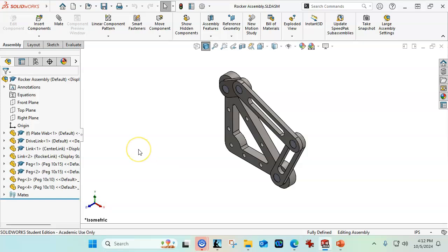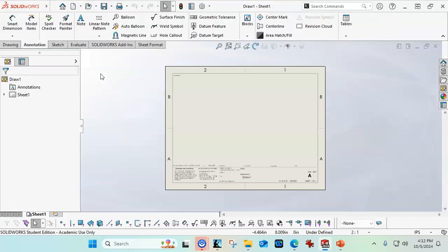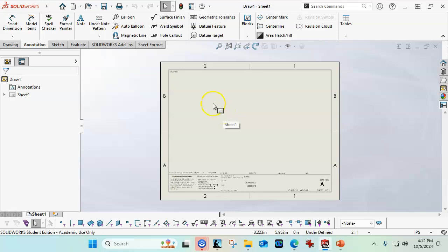All right, so when I did the alternate position on 510 or 511, whichever one that was, I created the configuration and changed the angle before I went into the drawing. Now on the demo and previously we've done different title blocks, so if you want to use the A landscape or you've created a title block, this is the one that was built in the demos. So pick up this sheet.